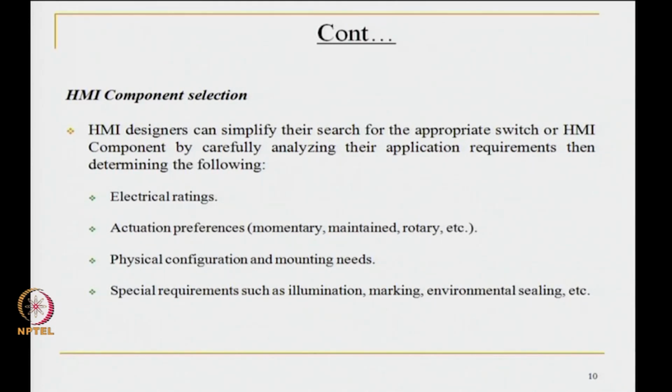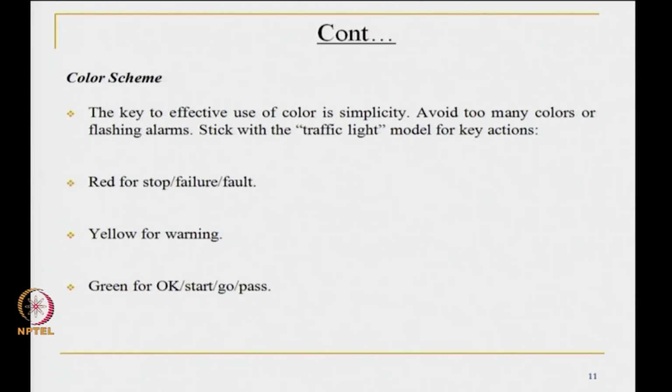Just as there are HMI component selections, so there is the issue of the color scheme, which is central to understanding the man-machine interaction. The key to effective use of color is simplicity, like everywhere else. The purpose is to avoid too many colors or flashing alarms. Stick with the traffic light model for the key action. If you stick to the traffic light model for key action, what is it that you get?